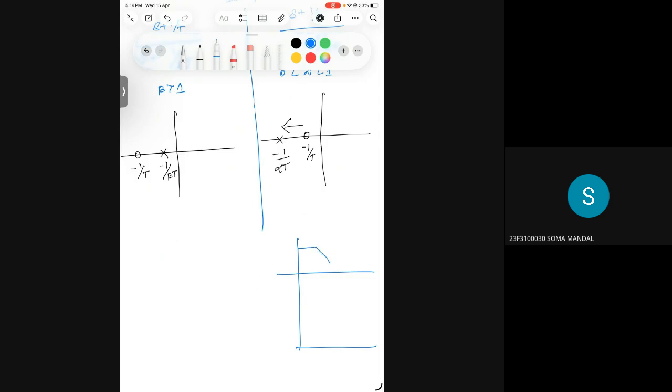It has a slope of minus 20 decibels per decade, and this starts at 0, and then some negative value it will come to. The gain margin will be a little negative. I am plotting the phase plot on the wrong side. Wait, this confusion always happens, but it shouldn't. So that is 0 degrees, this is minus 45 degrees, and this comes nearly to minus 180 degrees.